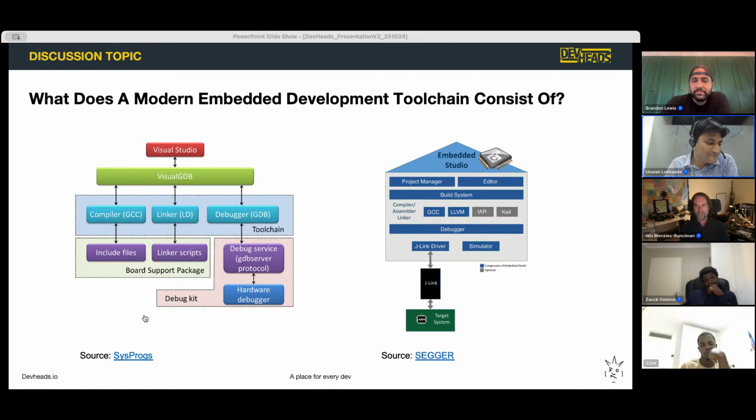Okay, so like Ming says, Ming started with where you have to compile everything. You have to build your tools and then you can use the tool. I entered into embedded when the tools were there. There were too many tools, and you have to test every one of them, and most of them will discourage you because the setting of the tools in IDE was very complex. So I have used quite a few tools in the past couple of years, like Yocto, Code and others. And right now I've just settled down with keeping things very simple. So mostly GCC, ARM toolchain, and also AVR GCC is good enough for me because I work with two portfolios, 8-bit and 32-bit.